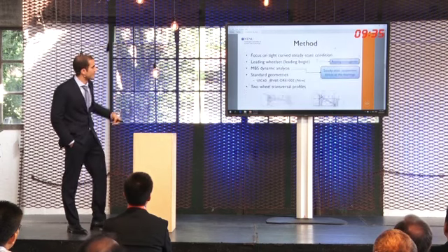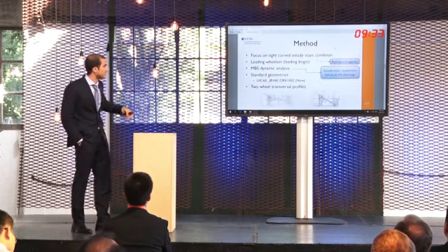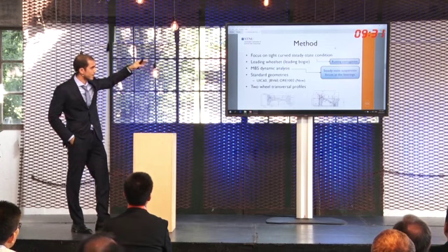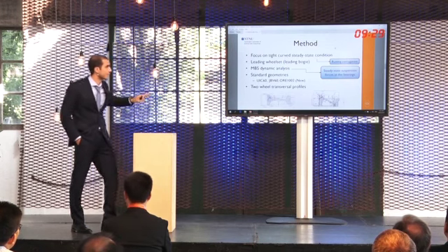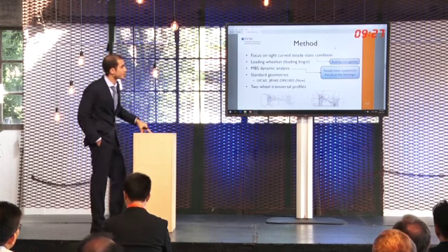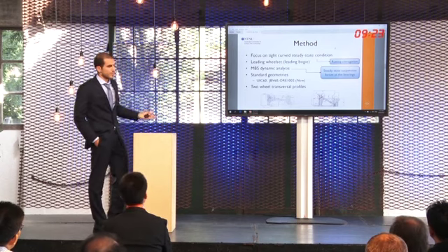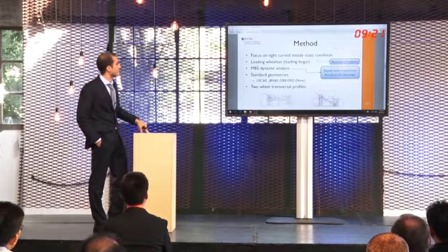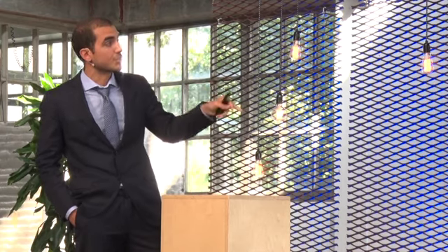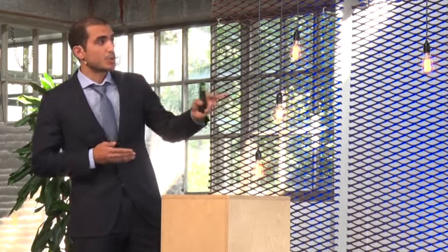Here, very quickly, the method of this analysis: we focus only on tight curve steady-state conditions, so we're just looking at rolling corrugation formation. In our finite element model, because we need the equations of motion of the system, we just consider the leading wheelset of the leading bogie of a one-car vehicle. In order to get the steady-state suspension forces at the bearings, we have preliminarily performed an MBS dynamic analysis.